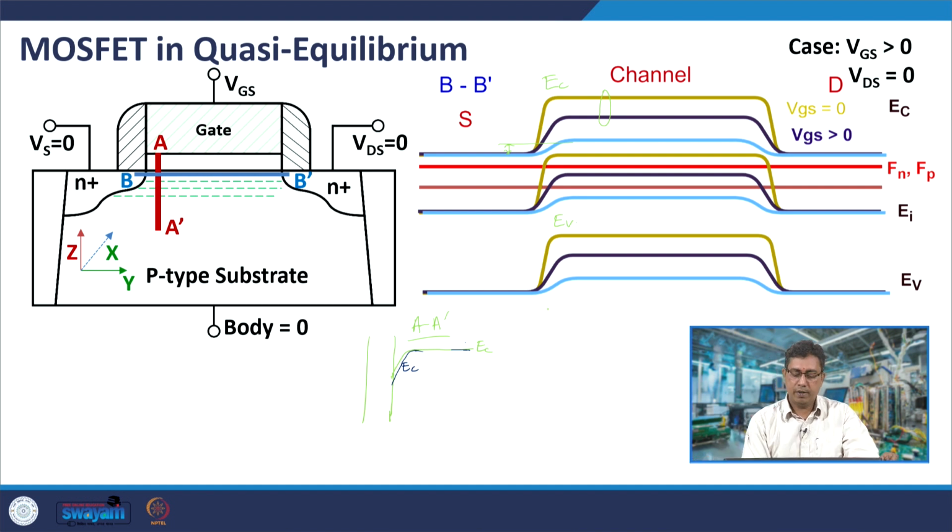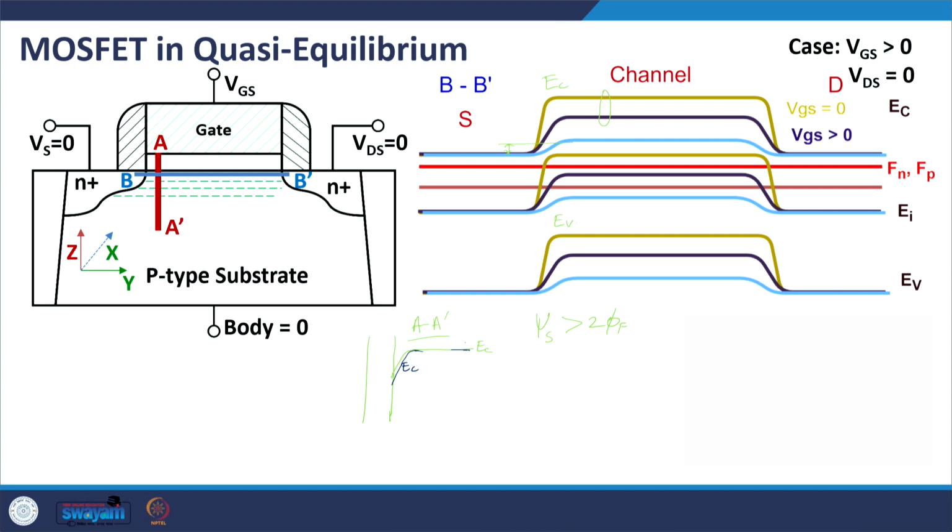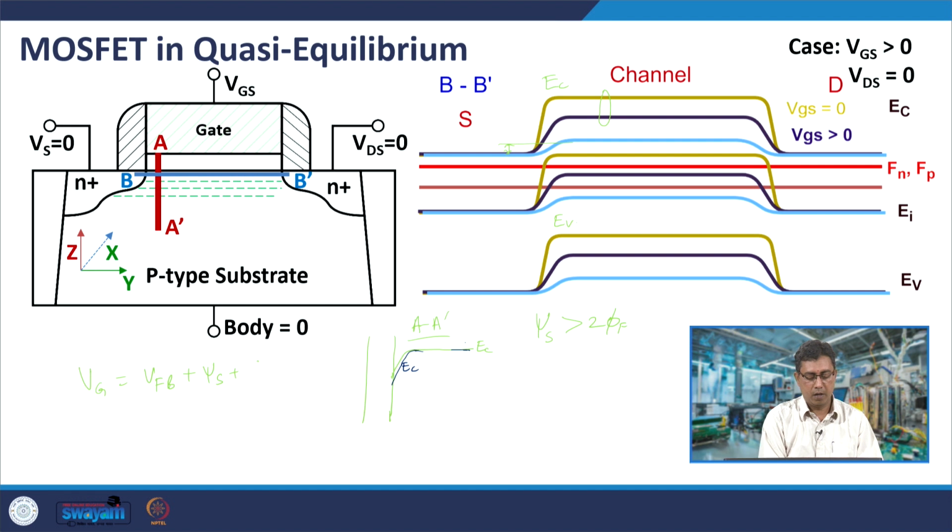That is why when we say that the surface potential is larger than 2 phi f, the electron concentration now increases exponentially with surface potential. Actually, as we had seen, the surface potential does not increase much, because as you can see from this relationship, this Q silicon is composed of inversion charge plus depletion charge, and this inversion charge, as you had seen, is proportional to an exponential of the surface potential.